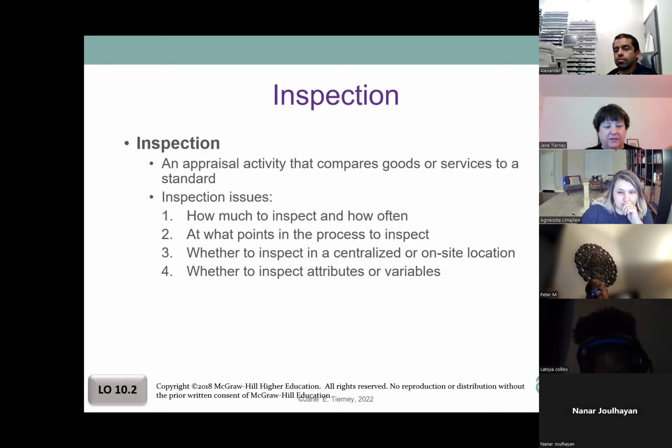And you can't do that to the foundation that you poured, right? You don't come out and take a jackhammer and say, oh, this is not supposed to crack until I put this much pressure on it, because you can ruin your whole foundation. So you pour a sample at the same time and you send that sample to the lab. They can do the testing there, and then they come back and say, yes, it's good or not. So there's different ways to do that.